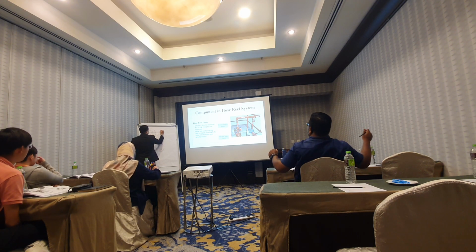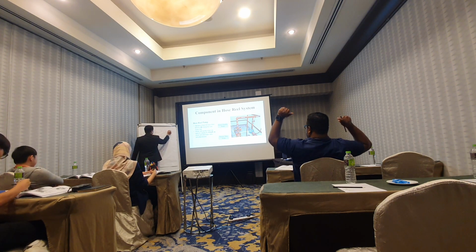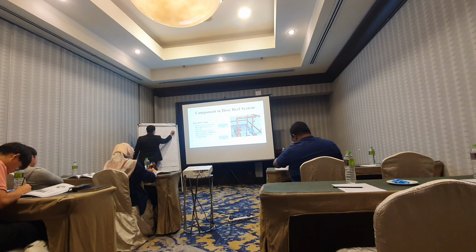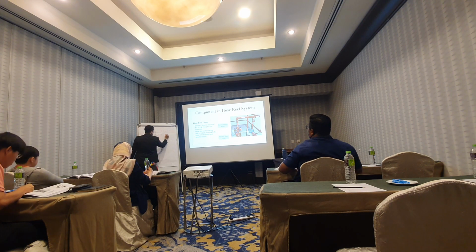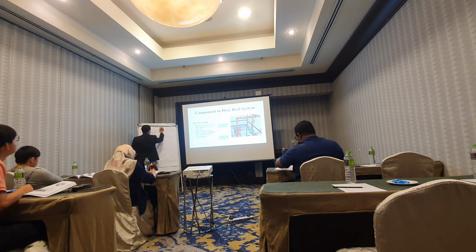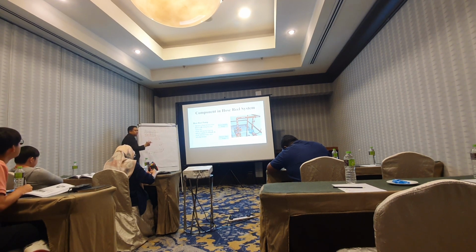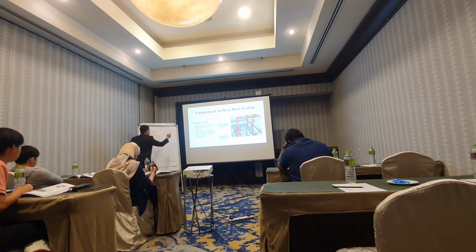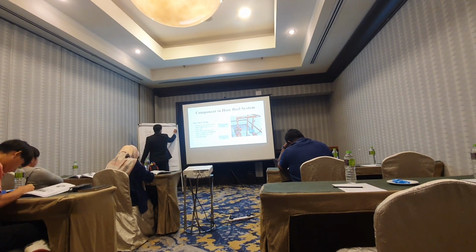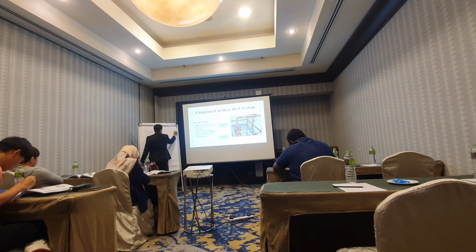30 liters per minute times 60 minutes, 1 hour, times the number of hose reels. Then you have the tank capacity. You can have more, but then you need to justify with the fire department. This is the design part, times the number of hose reels.